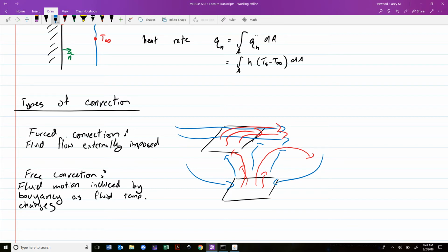Something I've noticed is whenever we turn on this projector, right, at the beginning of the day, you see this sort of roiling light pattern. And I think this is actually a really good illustration of what free convection looks like, because kind of off the bottom here, you can see where the bottom of the projector would be causing heat to flow upward, and you end up with this sort of recirculating pattern of flow.